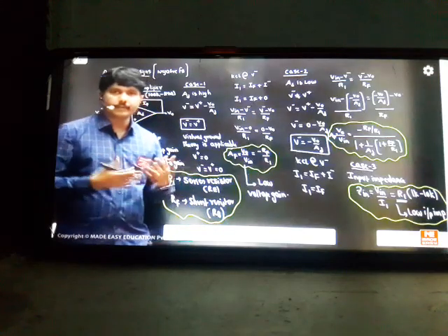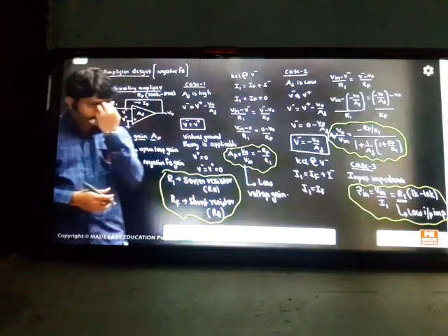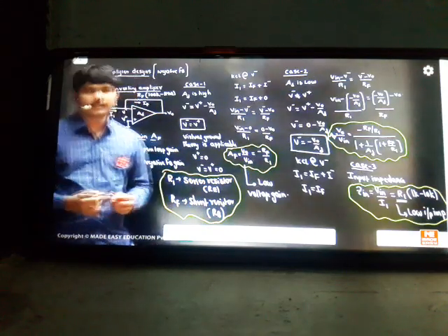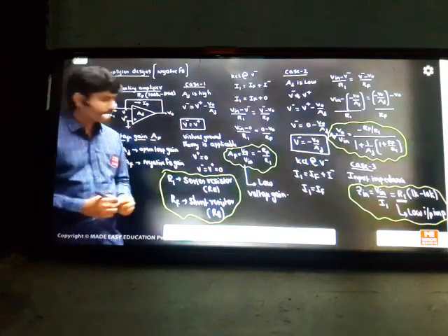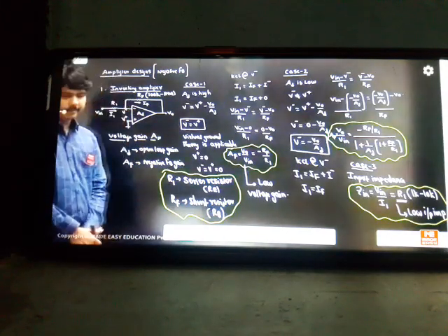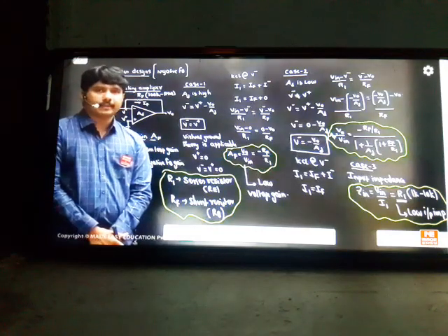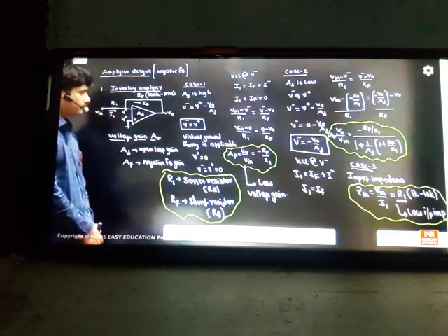Here resistors I will select, okay? In such a manner, it will maintain the linearity. That is the meaning. The resistors I can bring high also, low also. That is my control. You have to bring it to low. That is important. To maintain the linearity, the gain should be less. So can I expect it's clear? First topic. Let us go for the second design in the class. First design is completed. Let us go to the second design.